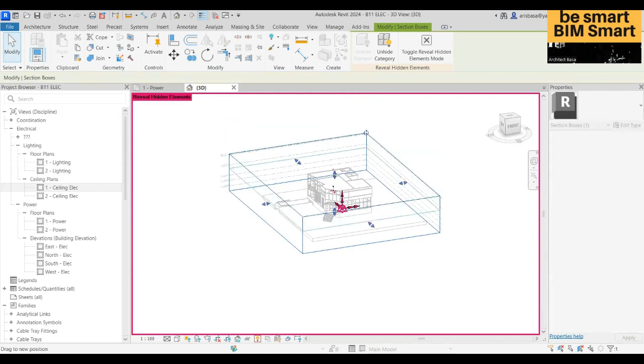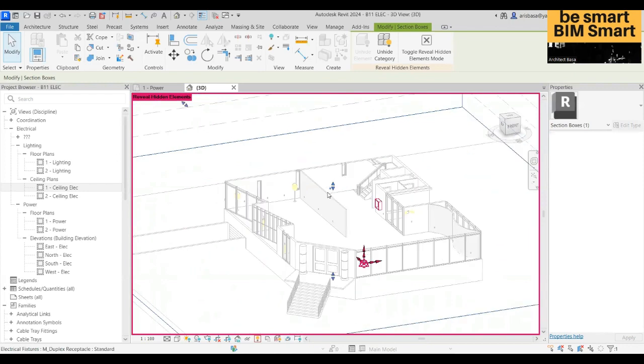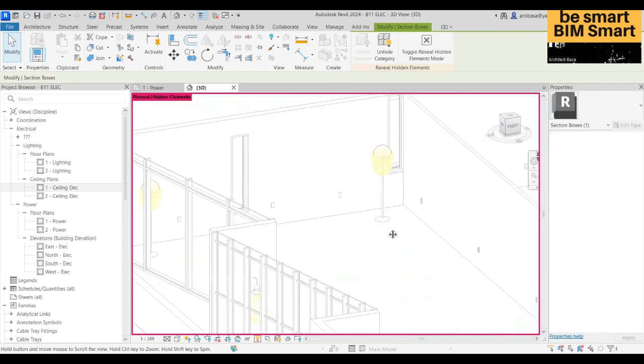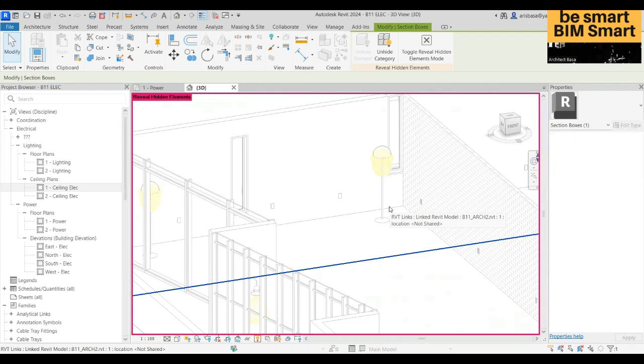All those lighting, none of those wiring is a model. They are lines but they are electrical connections. So this is what makes electrical in MEP different from the other parts of Revit. For example, this is creating a connection based on some mathematical calculation of the voltage of one part and another part. It is not actually a model. We are not modeling a wire, but we can, right?